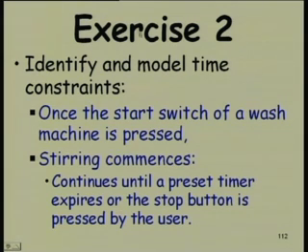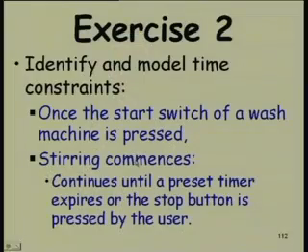We could have also an alternate example, like the water filling in the wash machine occurs as soon as you press water fill, and the water filling continues until the high level is sensed for the water in the wash machine, or the user presses the stop button. So, please try this one, because many times even though the concepts and the terminology are simple, unless we do one or two problems, we do not really get a feel of it.